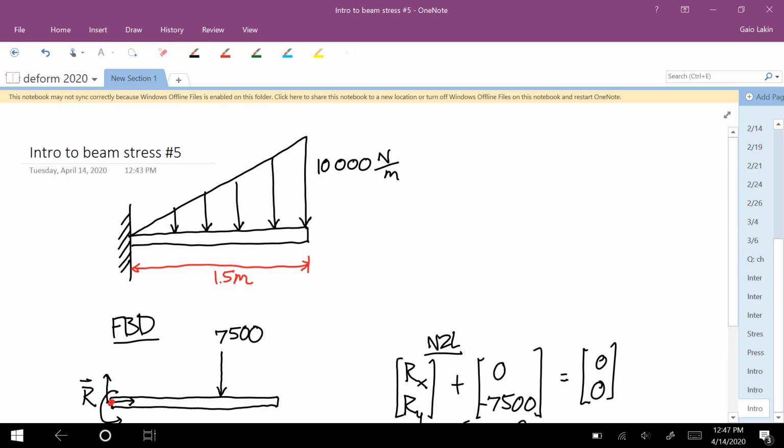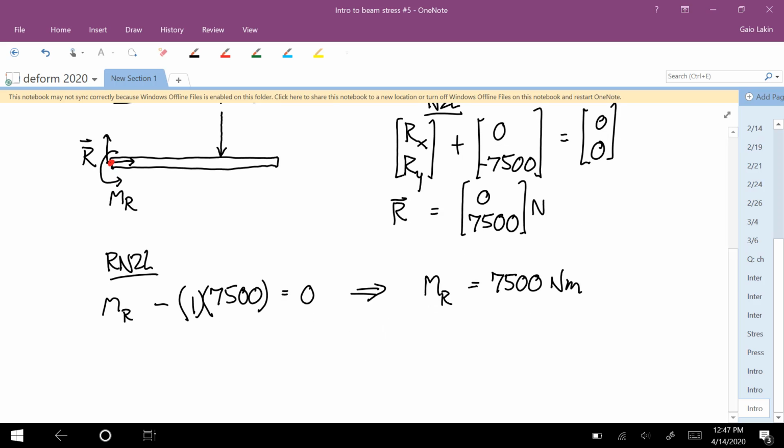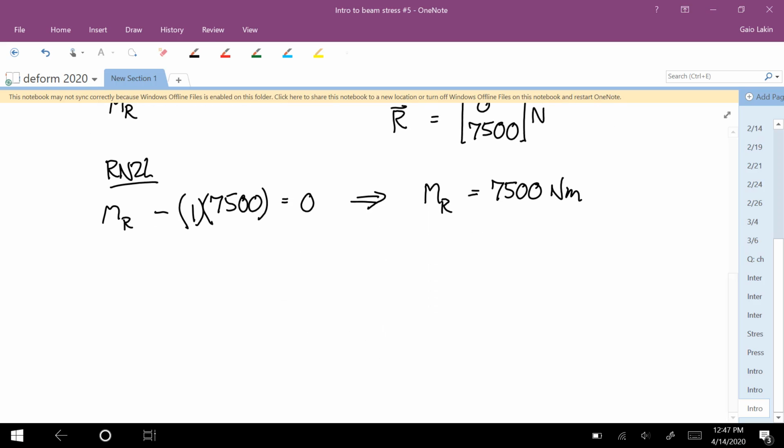What we really have is, if you looked at a free body diagram before we treated the distributed load as a point force, you would have loads at the left end, a distributed load function that's the same the whole way along the length, and that would be it. So there are no points where the subfunctions are going to change. And so we can just use one cut for the whole beam. So, okay, cut 1 represents all x values between 0 and 1.5.